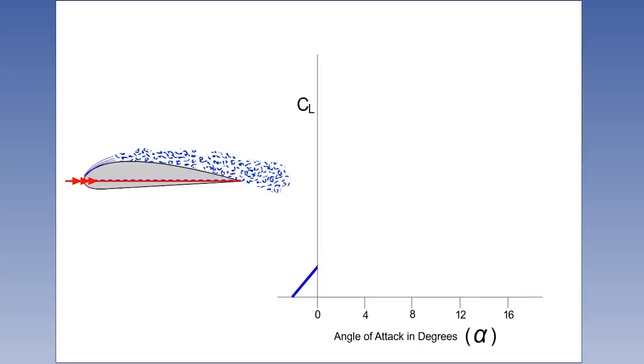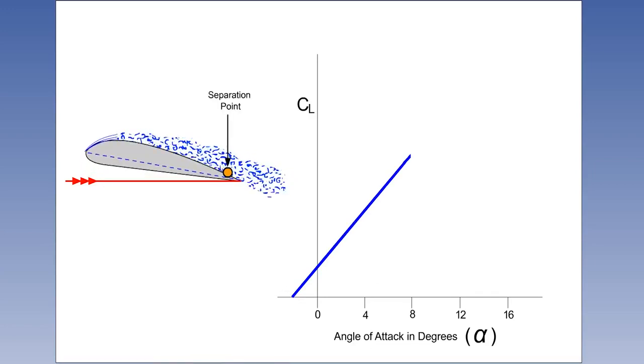The coefficient of lift, or CL, of an aerofoil increases with angle of attack up to a maximum, CL max. Any further increase above this critical angle of attack or stalling angle will make it impossible for the airflow to follow the upper contour of the wing smoothly. The flow will separate from the surface, causing CL to decrease and drag to increase rapidly. Since the CL max of an aerofoil corresponds to the minimum steady level flight speed, the 1g stall speed, it is an important point of reference. The stall, then, is caused by airflow separation, which occurs either when the boundary layer has insufficient energy or the adverse pressure gradient becomes too great.